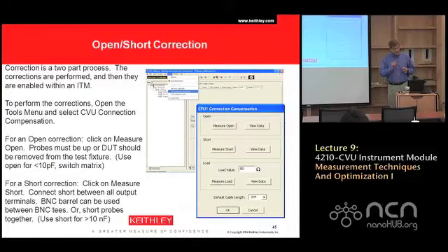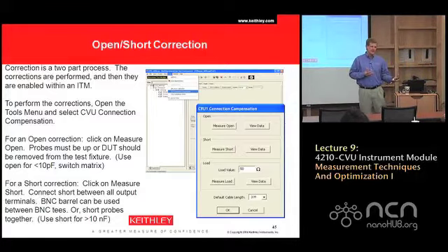All right, there's another important point here, and that is what we call our default cable length. Now, AC impedance meters are measuring AC amplitude and the phase relationship between the voltage and the current. So phase is an incredibly important part of this measurement. But we get a phase shift as we go down a cable.